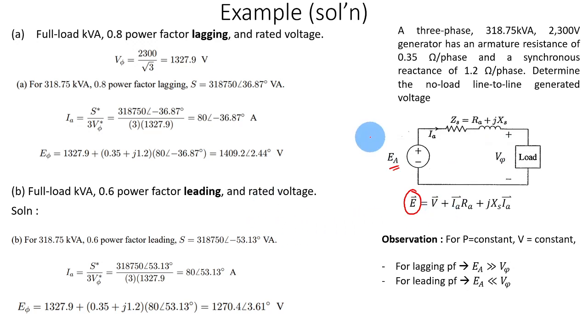Okay, and you can see that at different power factors, the voltage behaves differently. For example, for a lagging power factor, the generated induced EMF is larger than the phase voltage, and for a leading power factor, the EMF voltage is smaller than the phase voltage.